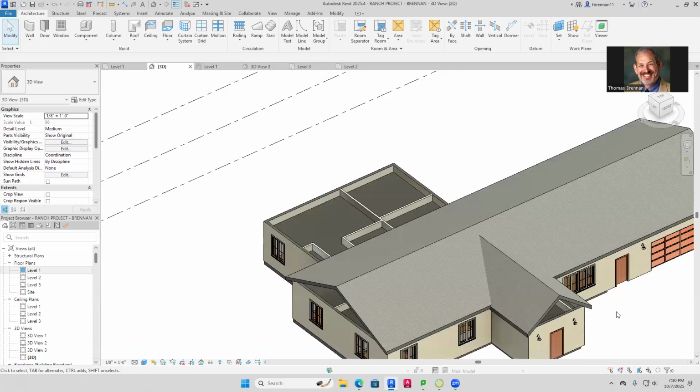So it's just a question of thinking with your roof lines. And as long as you get them in line, the buildings might not be a perfect alignment to get that there. Could you fudge something? Yes. And I just showed you how to do it. So just dink around with your roof line until it's right. Or you could make a flat roof, but slightly like a shed roof, just shedding a little bit of water. So there's a few ways to attack that, but you can do it.